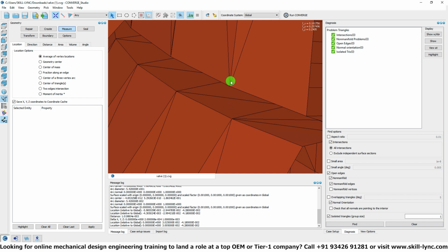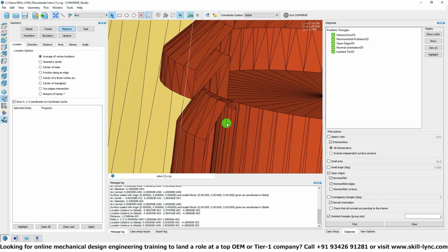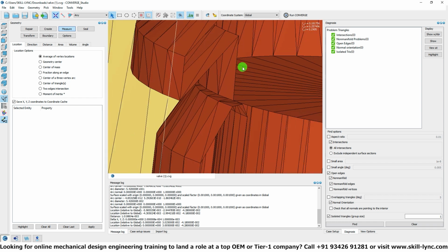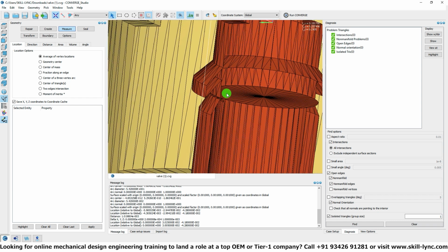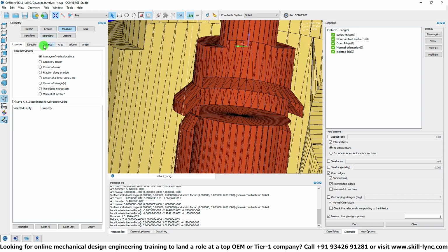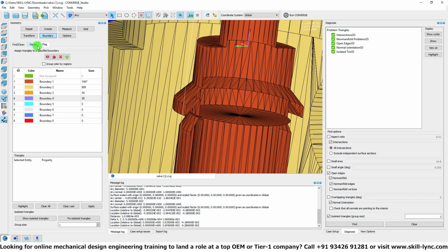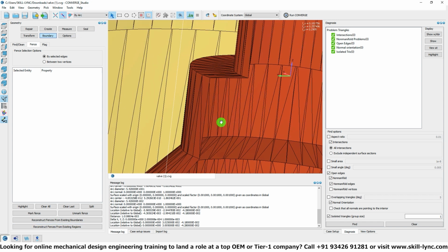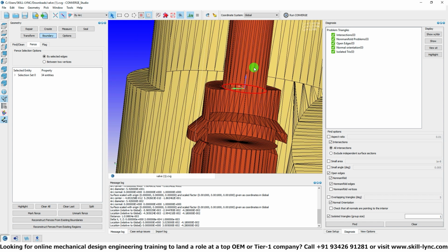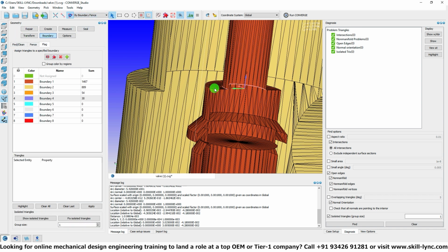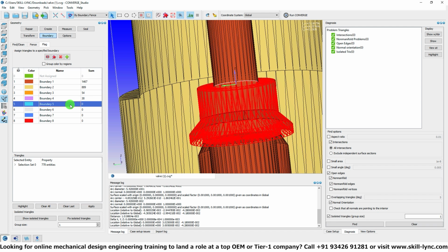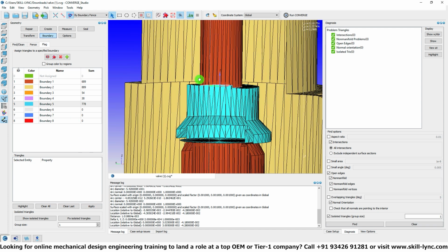It's super easy. So currently the lift is 1 millimeter, and for our first steady state case we want the lift to be 3 millimeters. That means we want to move this valve spindle by another 2 millimeters. So first I'm going to go to boundary, use the fence method, click on arc, select this guy right here, and create a boundary fence. Now I should be able to go to flag, use the boundary fence method, and select the entire spindle. Just by the preview you can see that we got the selection correctly. Let's put it to boundary number 5. Okay, so now we have our valve spindle.